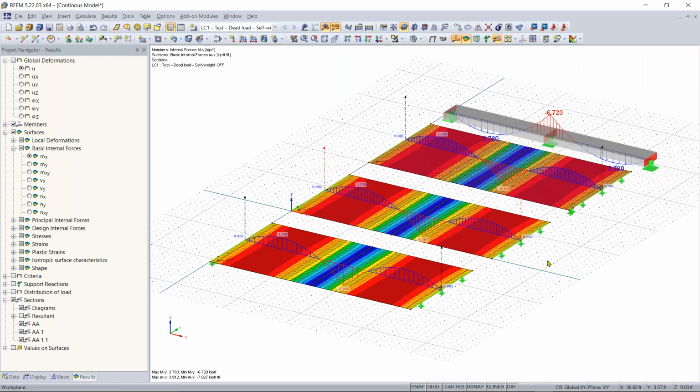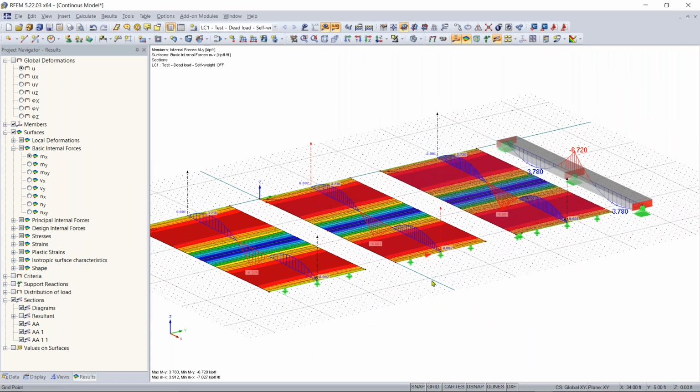But a good way to think of this is a brick element. If you're trying to model something that looks more like a brick, then probably a solid element would be better than a surface. So hopefully that answers your question. Awesome, great explanation.